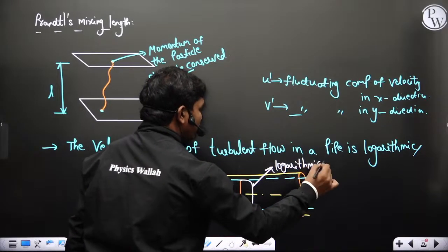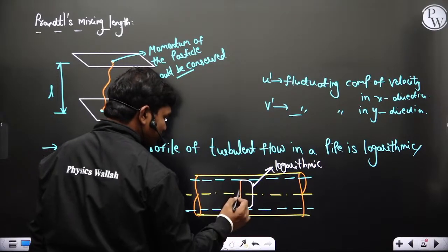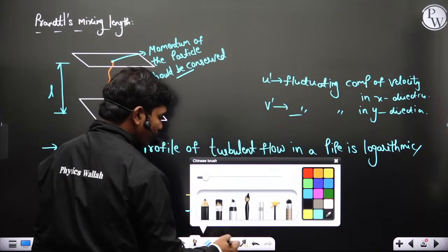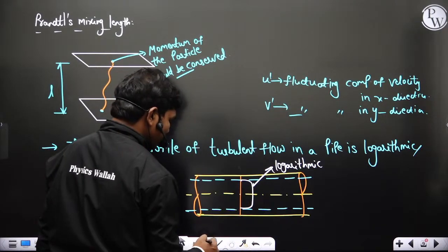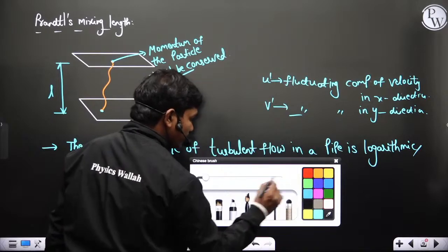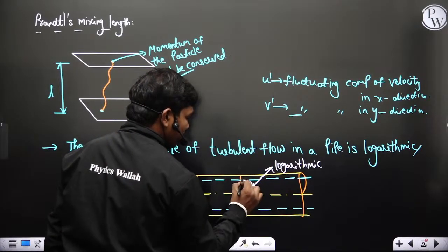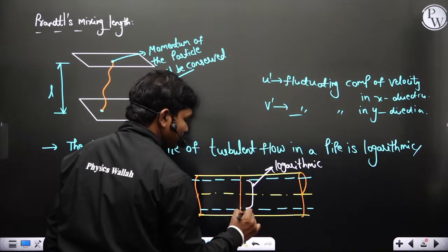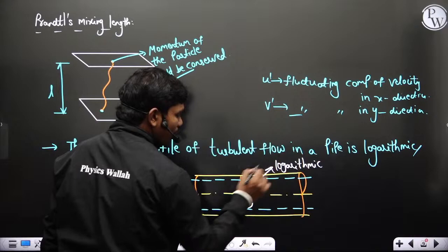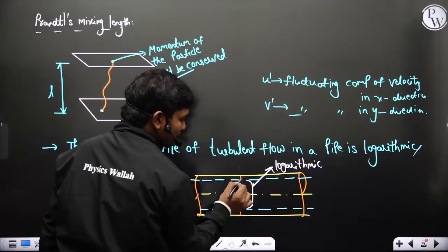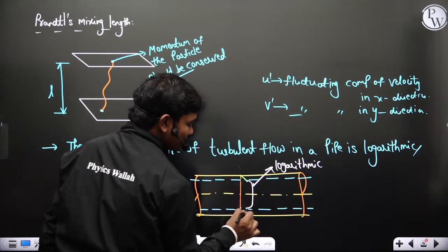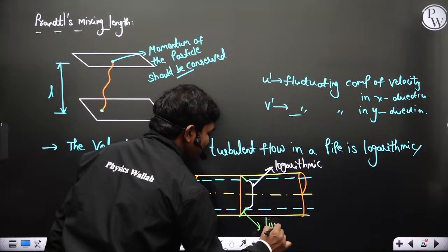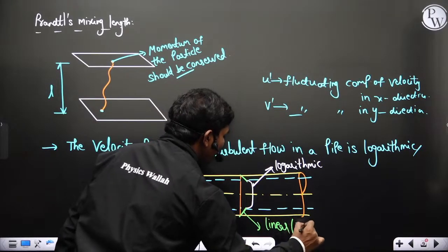But at the same section, if you take the particles which are close to the pipe wall, look here, the velocity is slightly, it is not 0. We shouldn't make it 0. Actually, some velocity is there by that time already because it's not the wall. So within this small layer of fluid, if you carefully observe, this variation will be linear. Okay, so this small variation in the sublaminar region is linear. The velocity profile is linear in the sublaminar layer.